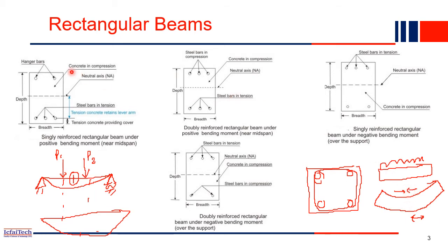That's why in a beam section, the bottom is subjected to tension. In earlier classes, you have seen that concrete is very weak in tension. Concrete cannot take much tension force. That's why wherever tension force is generated, we have to provide the reinforcing bars. So at the bottom, tension force is generated, whereas at the top it is compression force.